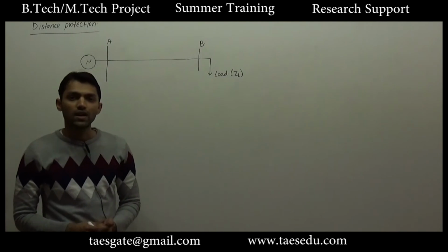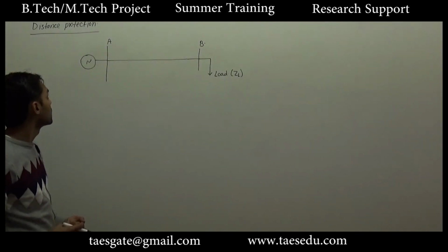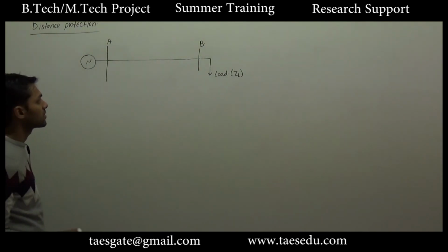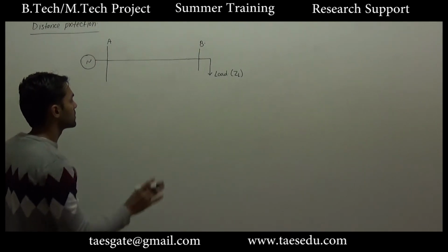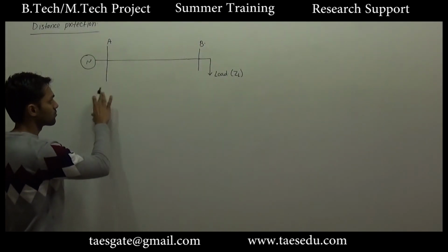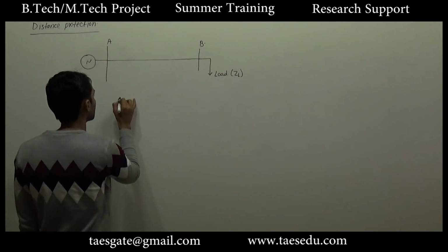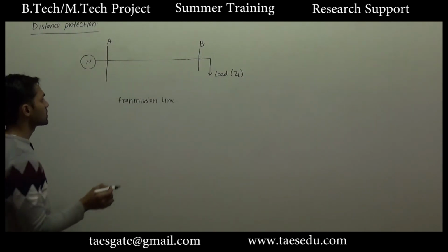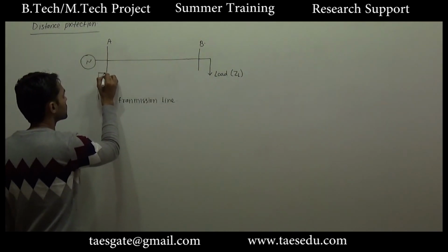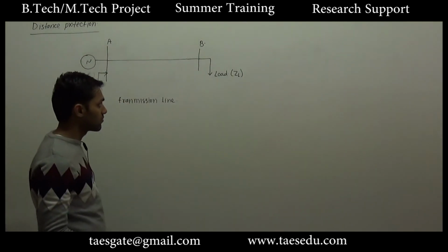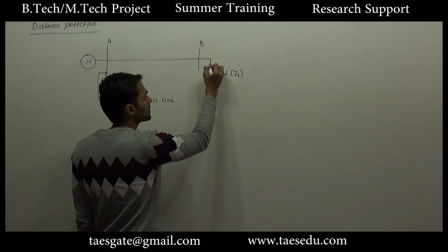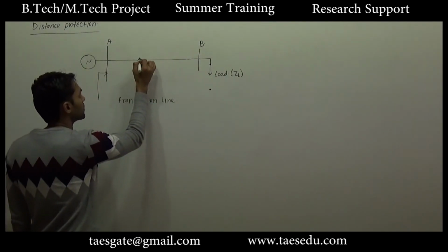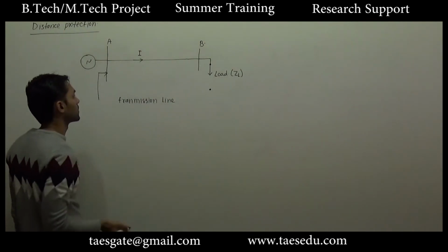Okay, after studying overcurrent relay and directional relay, now we will study distance protection or impedance relay. For studying the principle of this kind of relay, let us consider a simple system of a source and two buses. These two are connected through a transmission line. Now let us consider the impedance seen by the source. If no load is connected, or the load end is left open circuited, obviously there will not be any flow of current.